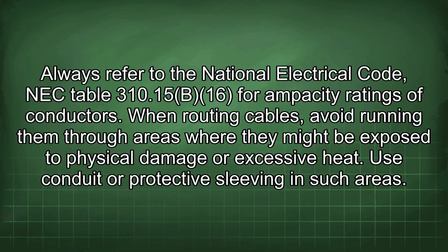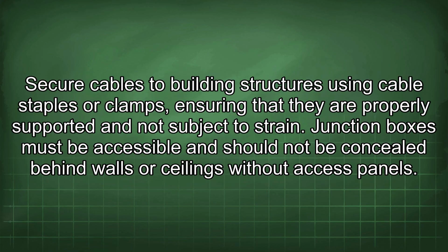When routing cables, avoid running them through areas where they might be exposed to physical damage or excessive heat. Use conduit or protective sleeving in such areas. Secure cables to building structures using cable staples or clamps, ensuring that they are properly supported and not subject to strain. Junction boxes must be accessible and should not be concealed behind walls or ceilings without access panels.